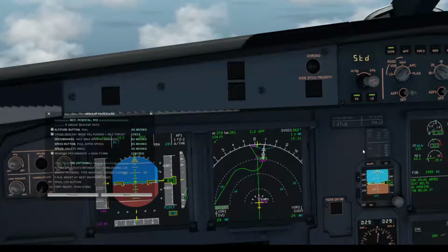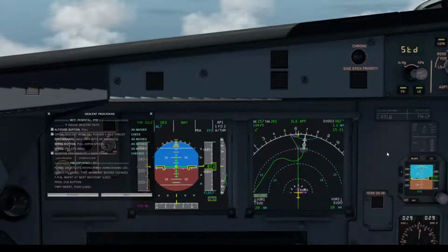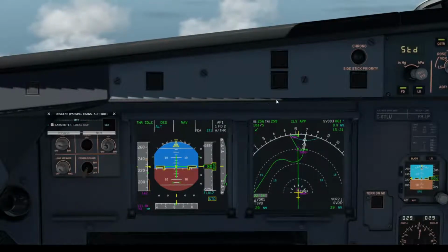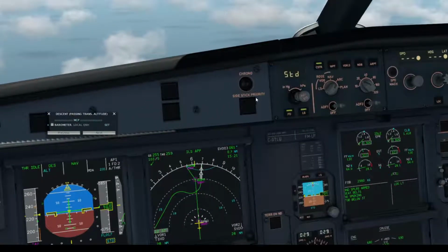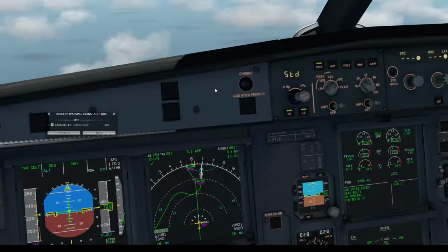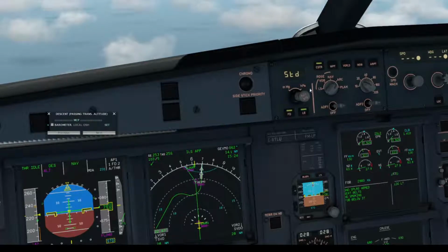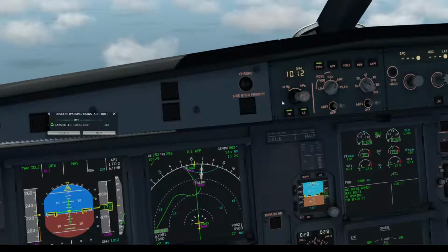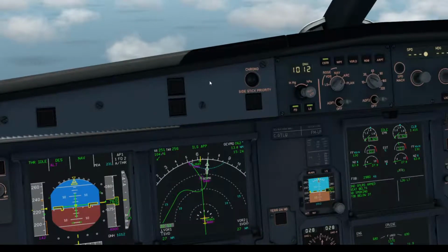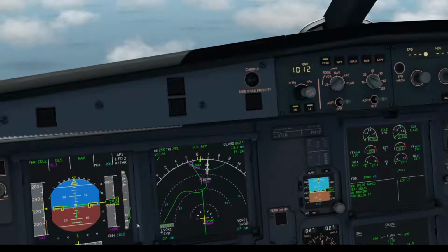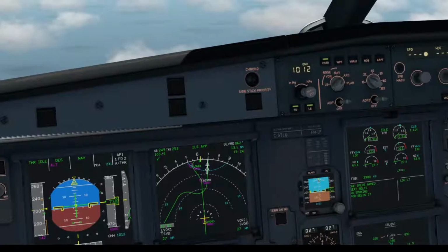Let's get a little bit more detail here, reduce the radar range. We can at this stage, if for instance ATC tells us descend to so and so many feet and not flight level XYZ, then we enable local QNH. Every time ATC tells you descend to 7,000 feet or 4,000 feet or anything with feet, you are automatically allowed to set the local QNH.